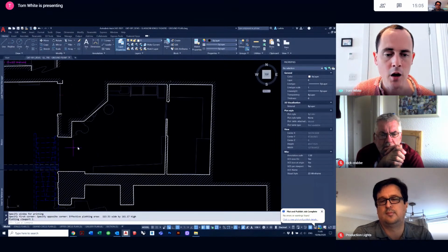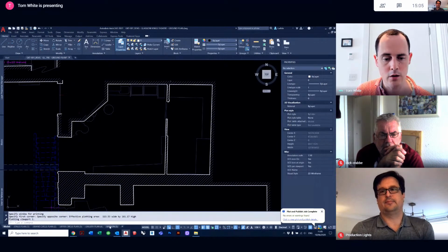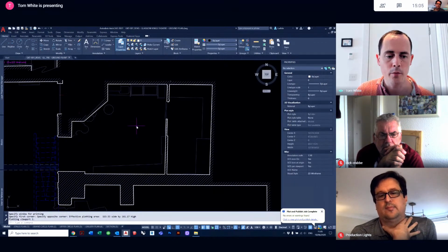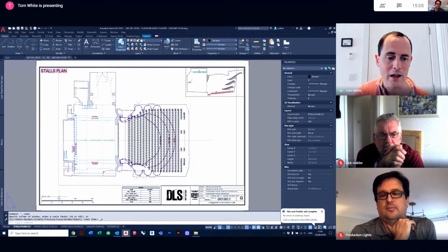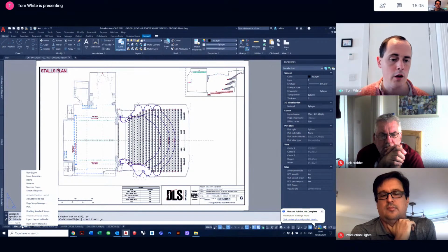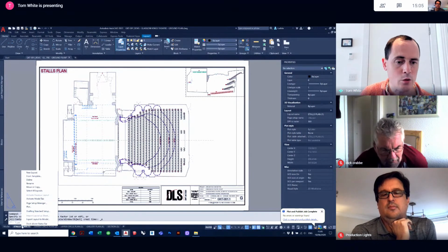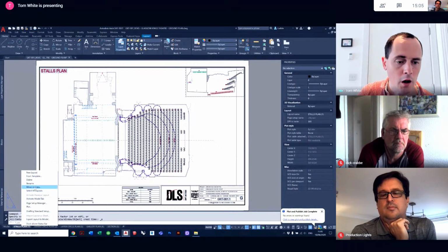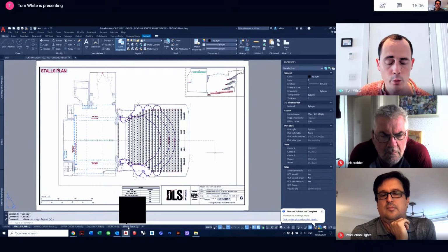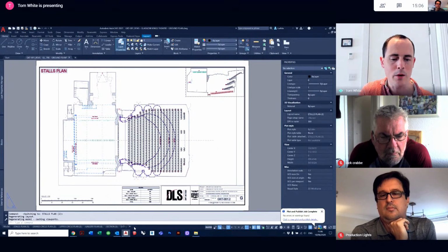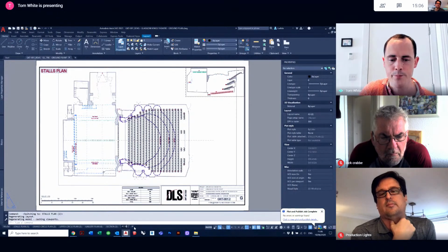In this circumstance, I have 5 layouts available to me. I'm not going to use those 5 layouts straight away. So I'm going to use a temporary layout, and I'm going to right-click on Stools Plan brackets 1. I'm going to do move or copy. I'm going to select the first one, do create copy, and click move to end. So it's going to be stool plan, and I'm just going to call it an A3 piece of paper, and I am going to do number 6.